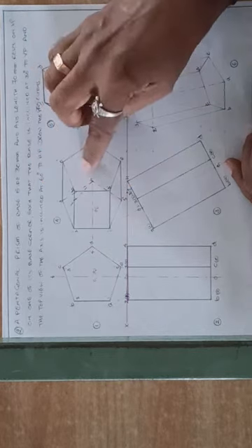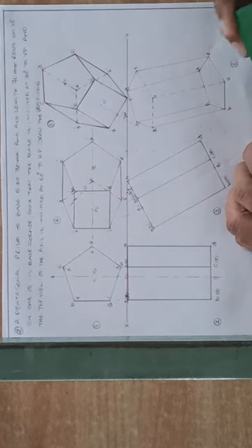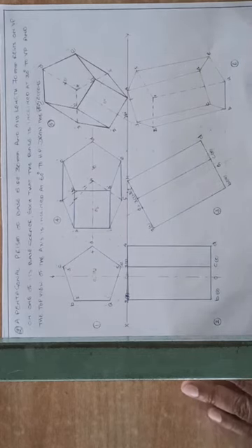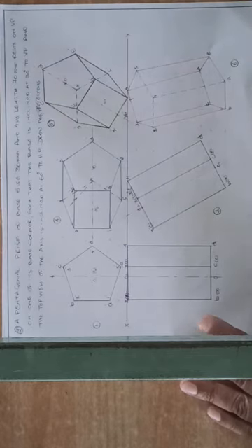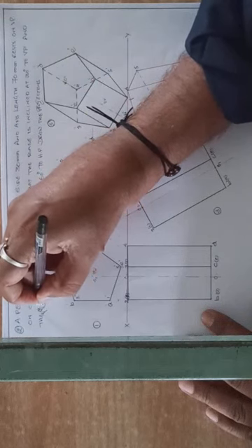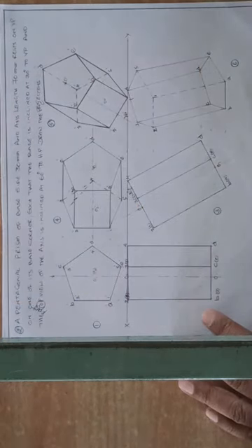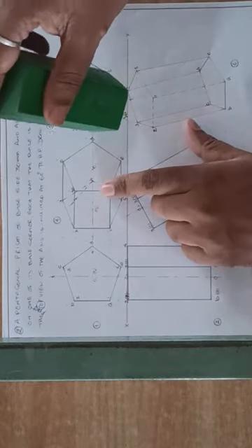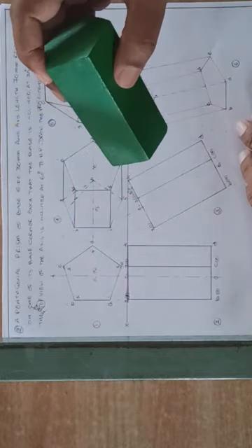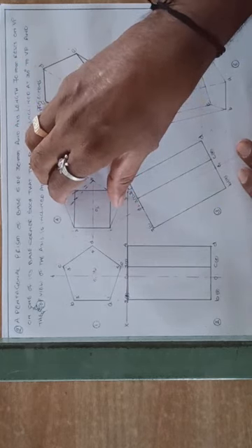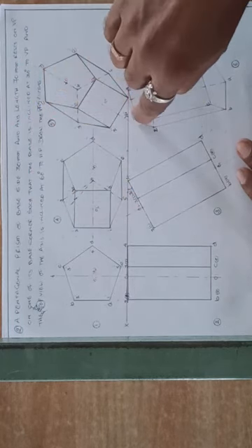So now coming to the third stage. Here this is the axis line. This axis line is inclined. Okay. It is inclined at 60 degrees to HP. So here, a small change. Here it is the front view of the axis. So now the axis, in front view, is inclined. This object is inclined at 60 degrees. That means we have to rotate this object so that the axis is inclined.